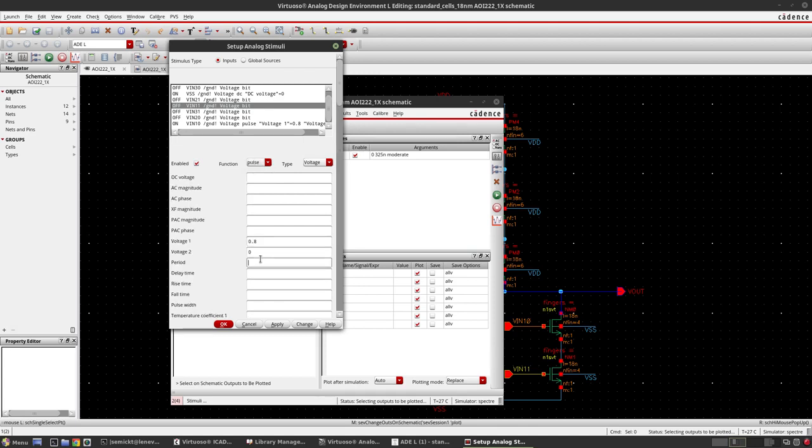This period will be 20 nano, double than the V10, and rise time 50 pico, fall time 50 pico, pulse width will be 10 nano because 50% of the duty cycle, right? So there we had 5 nano pulse width and 10 nano was the period. Here 20 nano is the period and 10 nano is the pulse width. Apply.